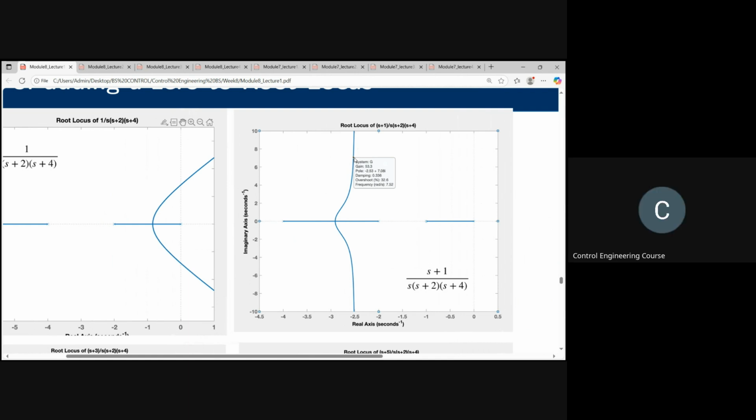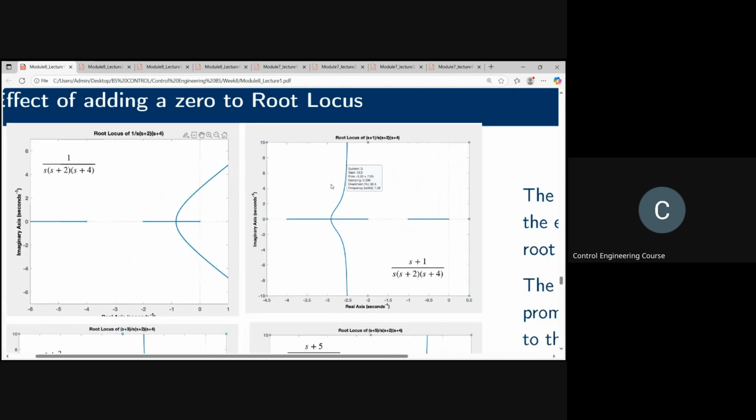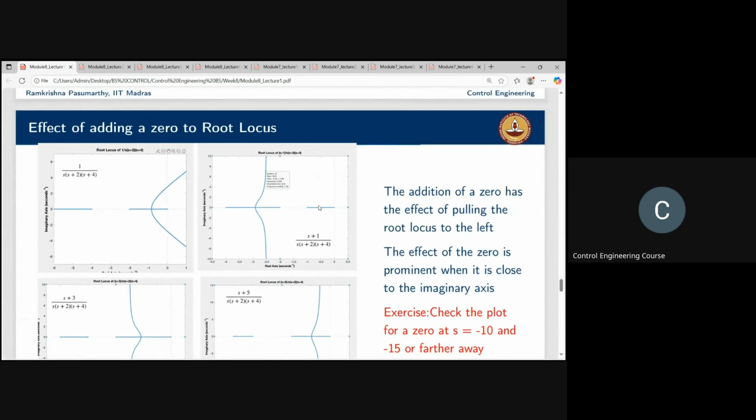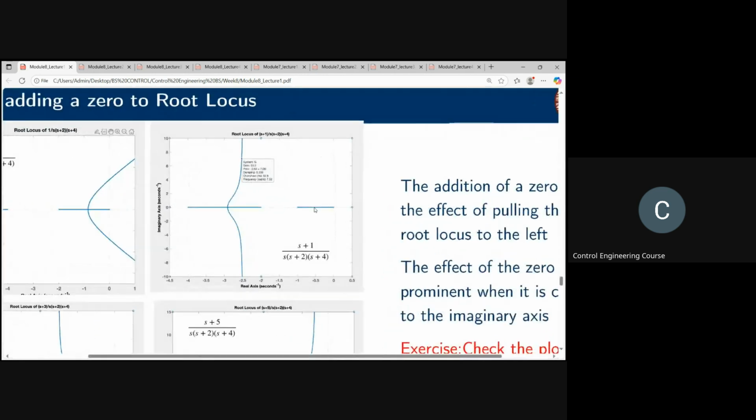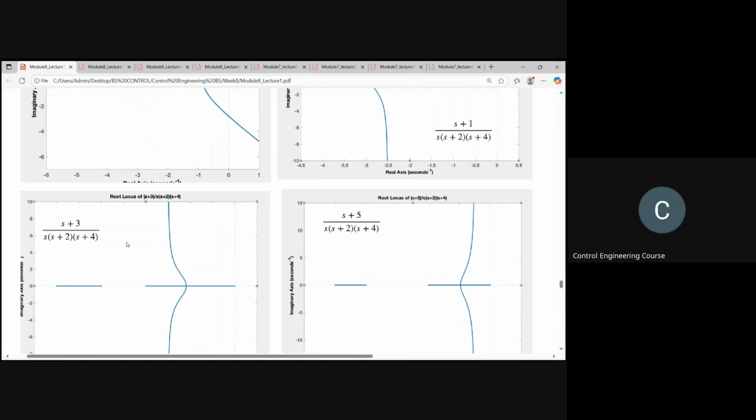Now if you choose a pole on that dotted line that they have shown, it will be -2.5, correct? Much more than what you want. You wanted at least -1, right? Now you get -2.5. But the thing is, this is not a dominant pole now, because there are poles closer than that here. Do you see? Yes, sir.